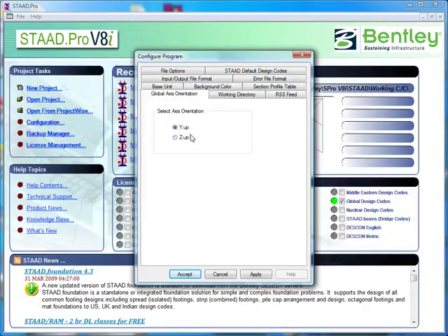The other thing that's of significance here is to note that while there is an option to reorient that basic coordinate system so that the z-axis is vertical, which might be useful in certain instances when data is being imported from some CAD program that's already assumed that the z-axis is vertical, be aware that making that switch may have the effect of ruling out your options to use certain other functions in the program, one of which is the automatic wind load generator.